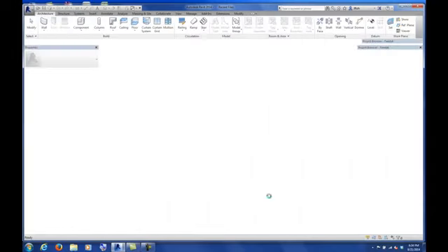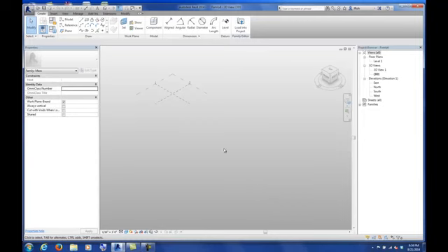That's going to bring us into basically what Revit refers to as the conceptual design environment. The conceptual design environment is actually made up of 3 family types. It's the one that we just opened, which is called just the massing template. There's another one called generic model adaptive, and we'll be getting into that today. And then the other one is curtain panel pattern-based family. So I'm going to be referring to those 3 as we go through the class, so you'll just have to get used to which one is which as we switch back and forth through the files.